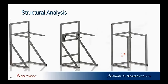So in this example, we've got 3 different frame concepts to support the bag. We've got a complete cantilever, then we have a cantilever with some bracing to try and dissipate the bending moment, and then we finally have the front supports to try and take that load straight down into the base of the structure.